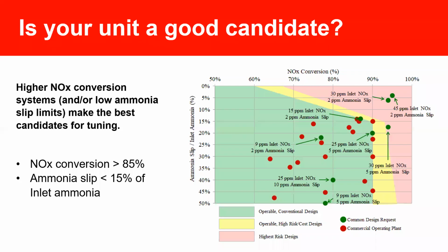That would correspond, if you're looking for 1 ppm of ammonia to convert 1 ppm NOx, to about 7% in your ratio of ammonia slip over ammonia fed. And that's where that particular point lies in this graph. As you go in the exact opposite direction of this area, you basically are looking for less NOx conversion performance and more of an ammonia slip limit.